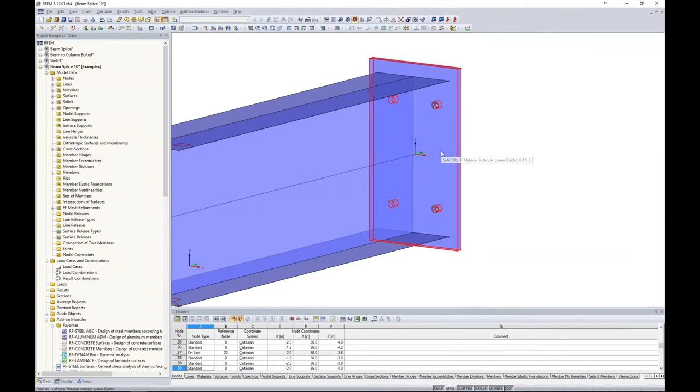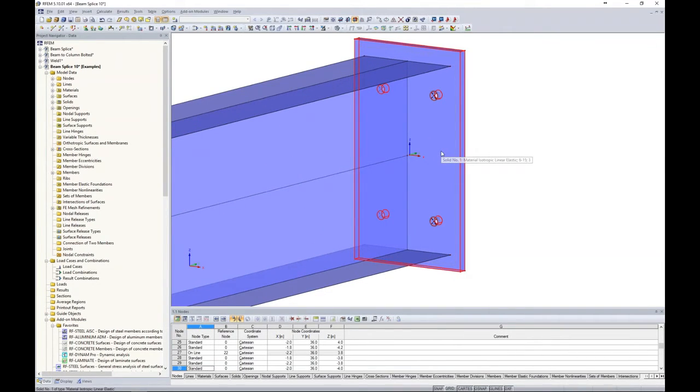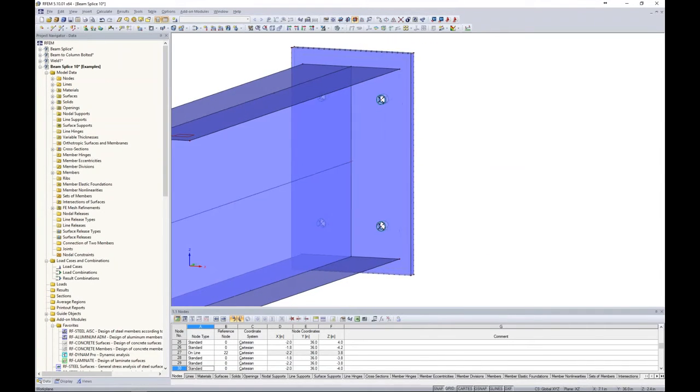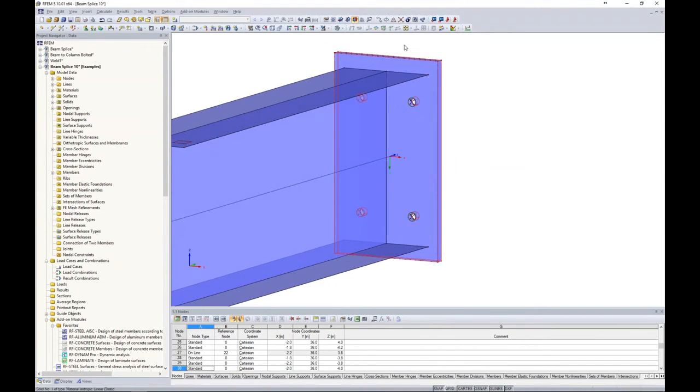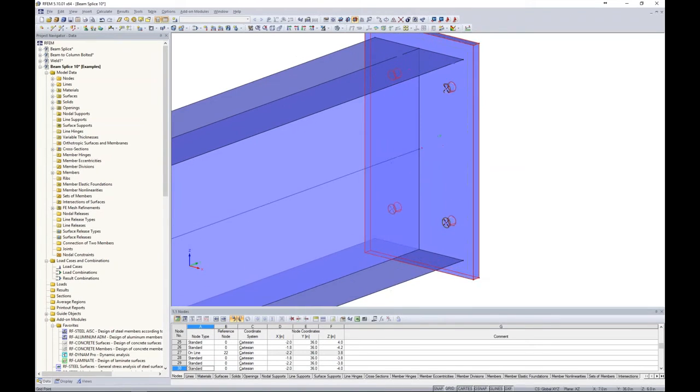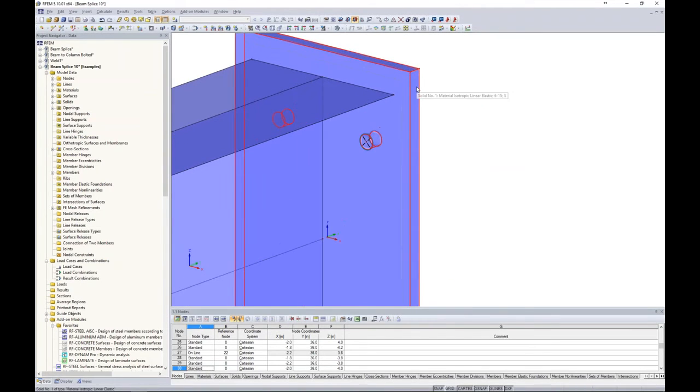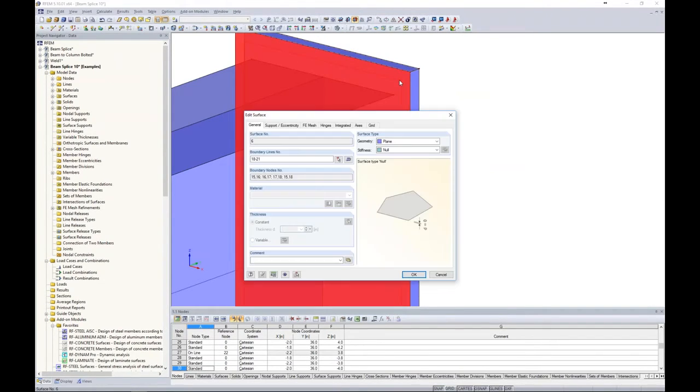It's created a solid element, so now we have a 3D element rather than a 2D element. We can see that those openings were carried through. That's all great. But when I'm looking at my surface elements, the solid is comprised of surface elements on every end. And that plate that we just defined, if I double click on it, it was automatically set to null. So that's what that checkbox did when we extruded this into a solid.